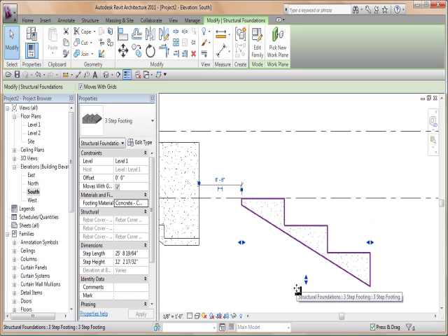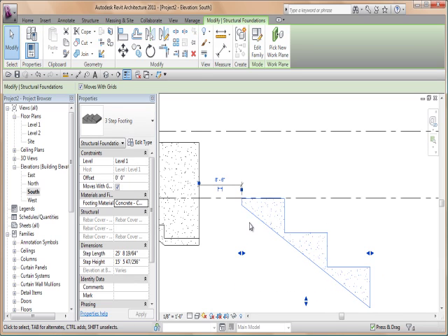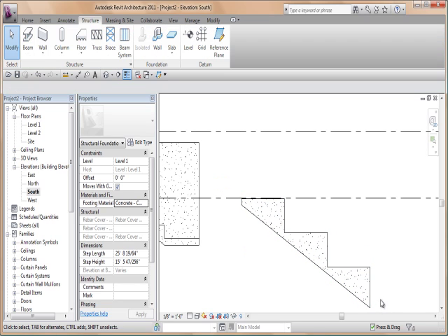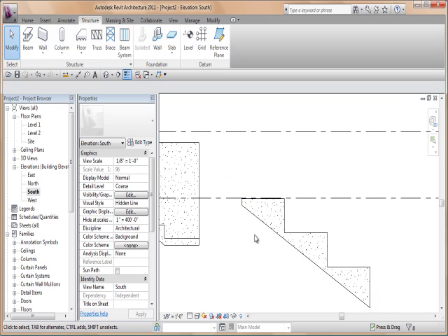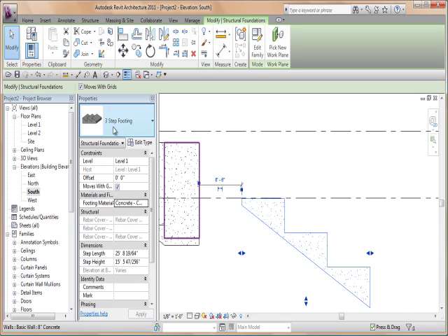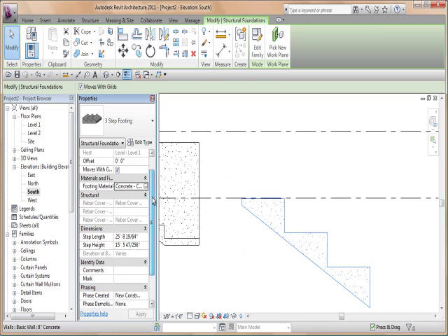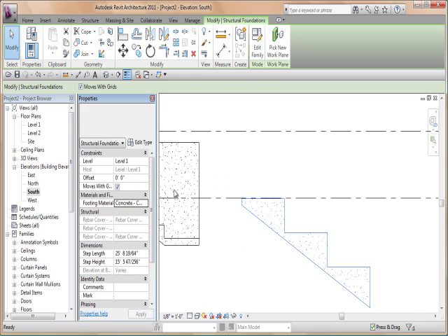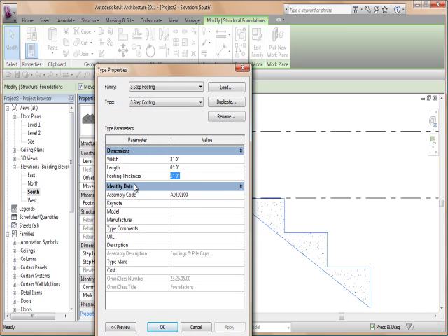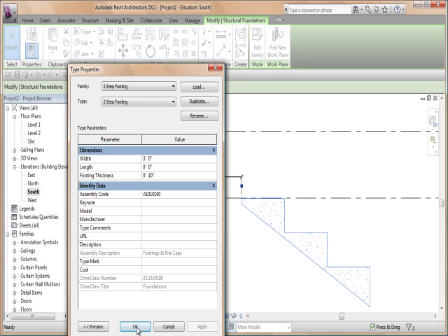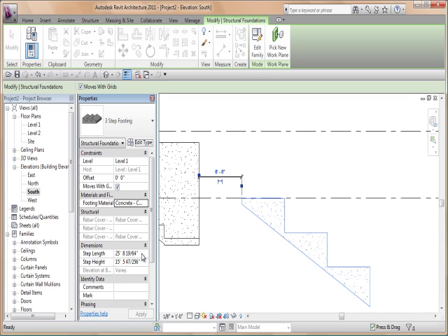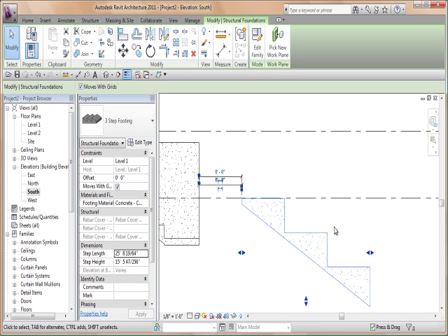So this is always going to be divided into 3 equal spaces, and this is always going to be divided, and then the thickness of the remaining part here, which matches up with this, is a property of the thickness. So I go into here and I go down to the properties of this, and I believe it's a type property, and I can go in here and change this to be 10 inches, and then hit apply, and it'll adjust that little bottom leg. Hitting OK.